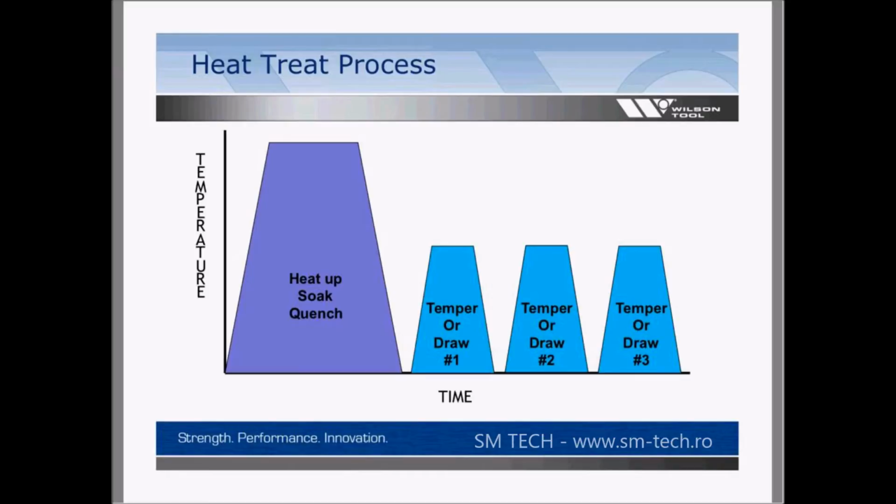So you want to get your material to the optimal hardness to begin with, which is your Rockwell, and then from there you're going to temper or draw that back down into a performance Rockwell. That way you can get into a higher 62 to 64 range in your 10Vs and your M4s to get some good wear resistance, or maybe even into that 58, 60 in your 3V range materials to get better toughness.